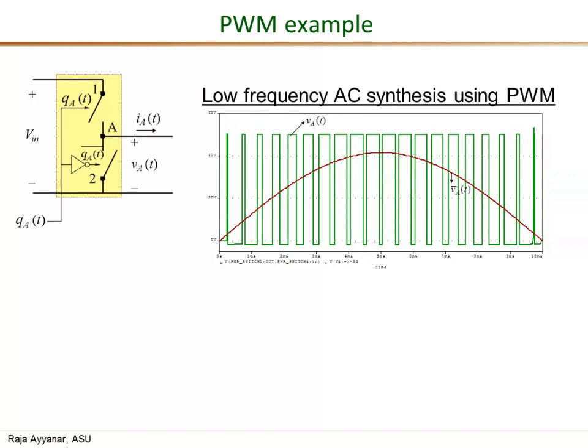So all we have to do is, let's say we are near the zero cross of the sine wave, somewhere in this region, then the pulse width is very, very small, negligibly small near the zero crossing. Whereas somewhere near the peak of the sine wave, you can see that within one period, which is from this point up to this point, the T on interval is a very large portion. So the duty ratio is very high near the peak.